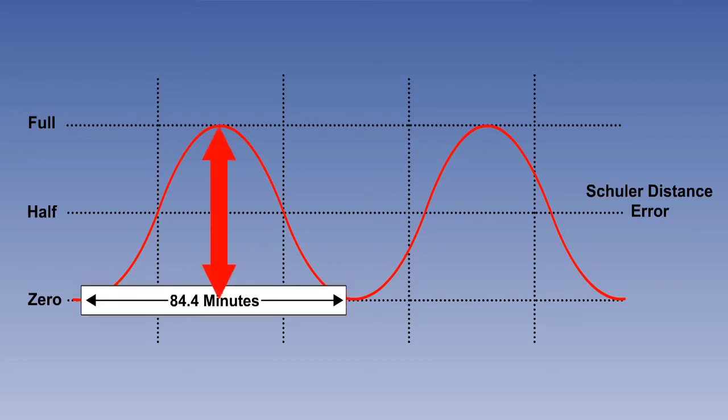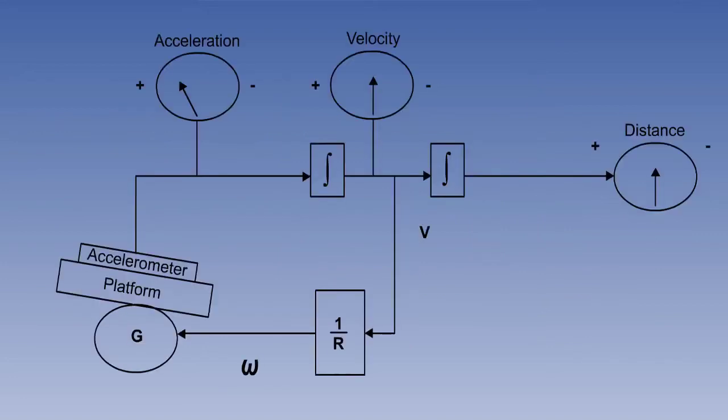The maximum value of the Schuler error does not increase with time. Whatever the amplitude of the first cycle, all subsequent cycles will have the same amplitude. The oscillation is self-sustaining because the system is resonating at its natural frequency. Most people find the explanation of Schuler errors using the moving diagram a little complicated, and you are not expected to be able to remember it in detail.